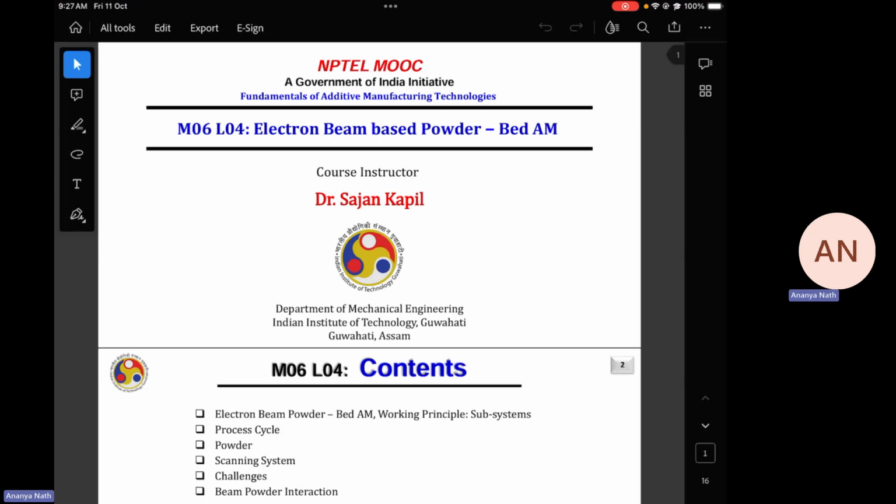So everything will be the same, only instead of a laser, we are using an electron beam. Now, electrons are very light because they sit inside the atom. If the atom is light, then the electron is lighter. It is focused at a particular position over the build plate, coming all the way from the head to the substrate. In between, if it by chance hits any other particle, for example an air particle like nitrogen, oxygen, carbon dioxide, then it can get deflected from its required or desired path. That is why the chamber of electron beam melting is always supposed to be vacuumed.